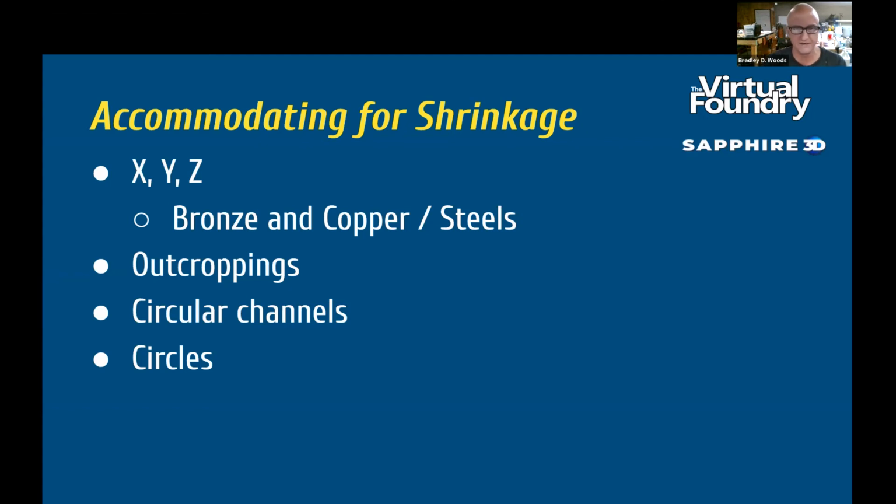Shrinkage and density kind of go hand in hand. The more dense you want your part, the more you're going to need to shrink it, and you can do this by raising the temperature or extending the sintering time. So there's that relationship between density, shrinkage, and part shape as well. The more dense you want your part, the more it's going to shrink, and the more subject it is to the part shape warping a little bit as you continue to shrink it. So all of those things need to be considered as you're thinking about your part design, and after you've done a couple of trials to see how the part comes out, making some adjustments to that design up front.